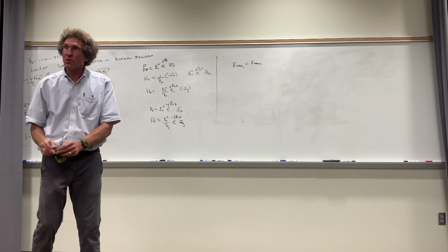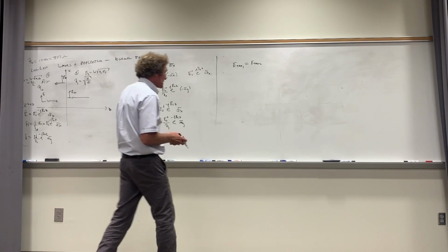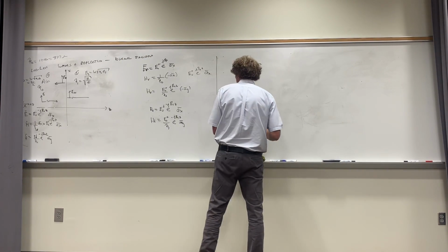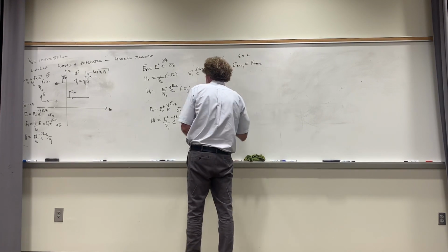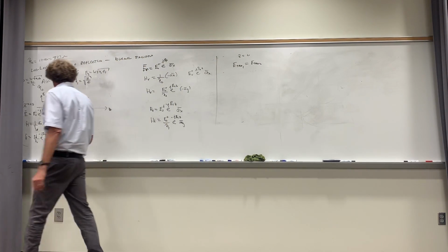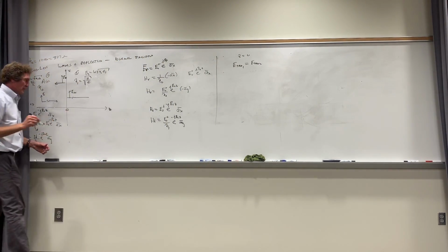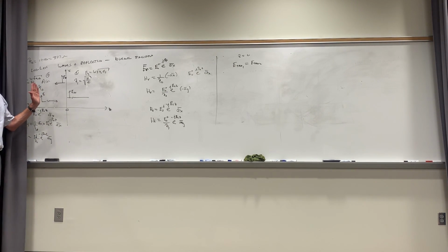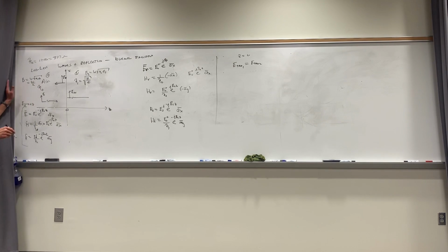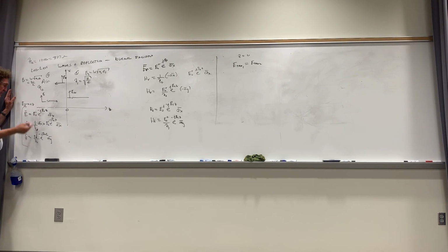All right? So when we talk about E tan 1 is E tan 2, what we do is we look at the point z equals 0 and we equate them. And it's smart to always put the separation between two regions at z equals 0. Follow me that, class? So when I look at this, well, this is the description of the electric field in region 1. The incident field is E0 incident times e to the minus j beta z. If z is 0, it's just E0 incident, right?